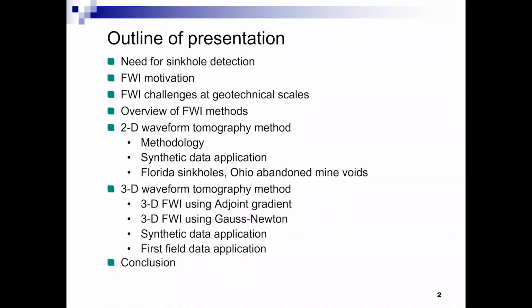Yeah, so you have shear and compression, shear and P wave. But for an air-filled void, we have a P wave of about 300 meters per second. Water-filled void, we have 1500 meters per second.